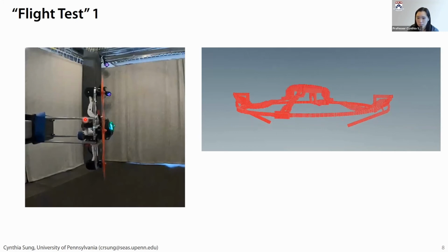And this is because there's an extra rotational degree of freedom in the system that we did not account for when we enforced symmetry. And so this is one place where some of the design simplifications that you might want to make as an expert designer to make the problem easier might actually work against you. And so in this case, we said, well, what are we going to do? We need to figure out how to make sure that the system doesn't encounter these other modes of deformation that might interfere with the behavior of the design.